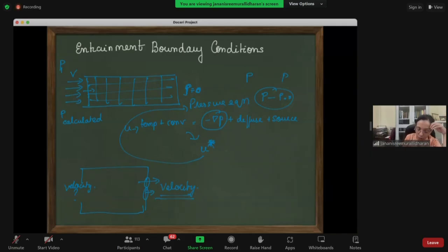So then I will have to say, fine, let me give you a pressure, ideally, right? But I've already provided the velocity outside. So if I give a pressure value here, it's not going to be too stable. I don't know the pressure very strongly either, because I don't know the velocity, so it will not be able to correlate the velocity versus the pressure. So what people do in these conditions is they go to the stagnation pressure.